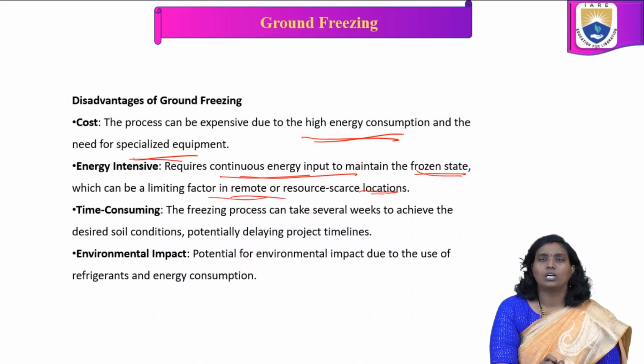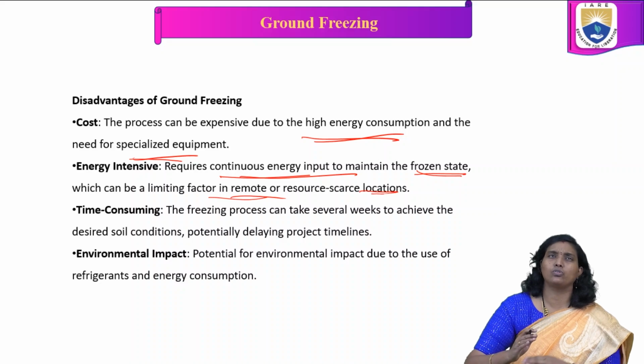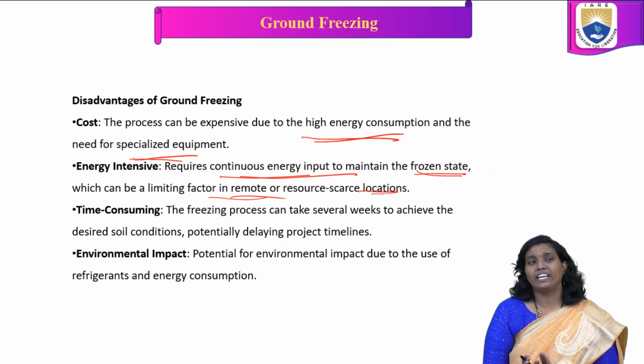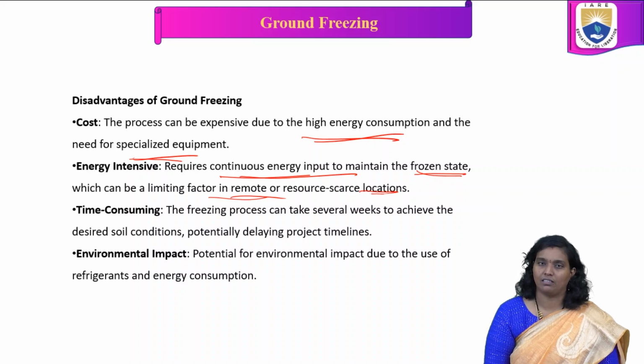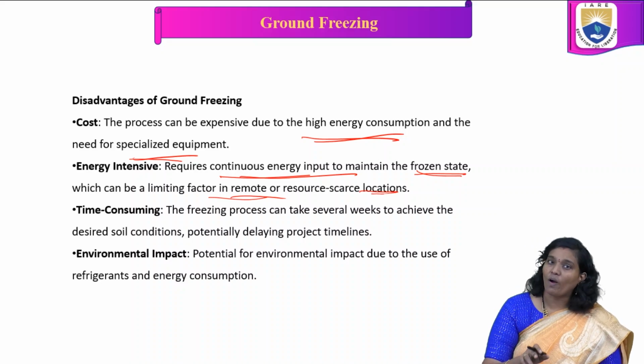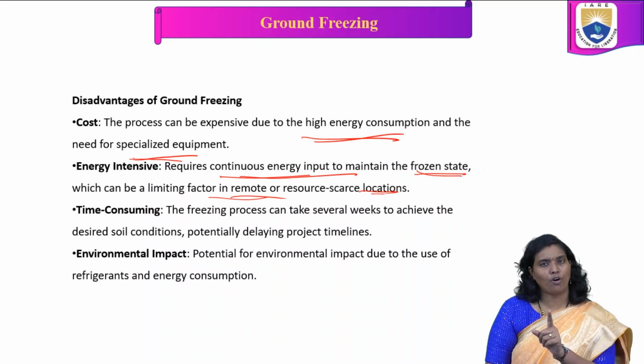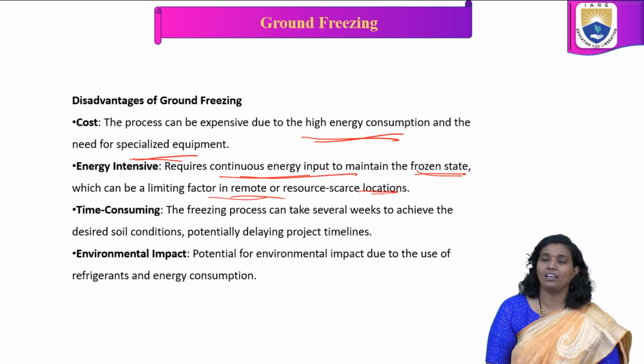And also it is time consuming. The freezing process can take several weeks. It takes some time, depending upon how much region is going to be frozen, the soil condition, which type of process we are using, how much energy we are spending, and whether we are continuously maintaining it or not.